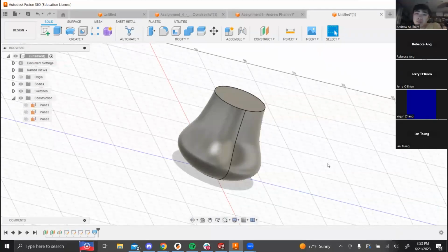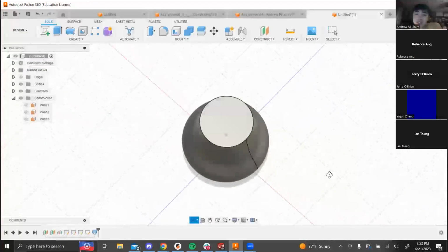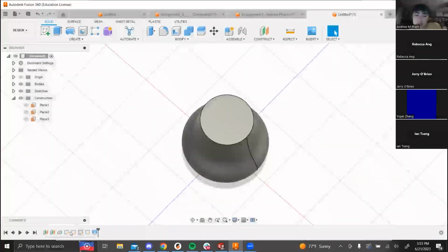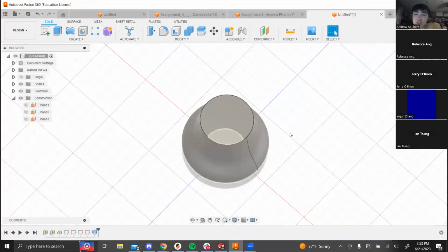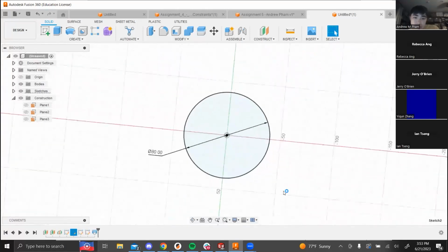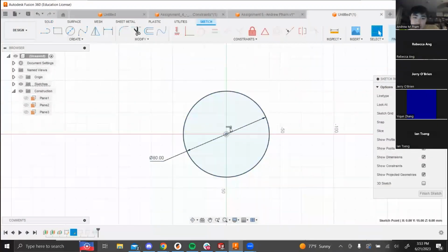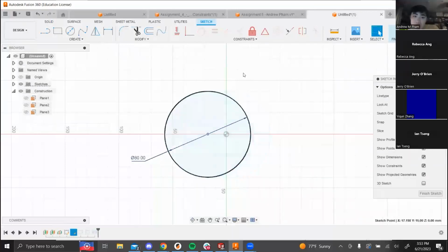The reason why all of these are in a nice straight line is because I drew all my sketches with the circles at the origin, so they are automatically lined up in this case. But say I edit the sketch, and I delete the coincident constraint with the origin.